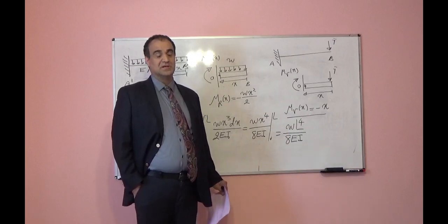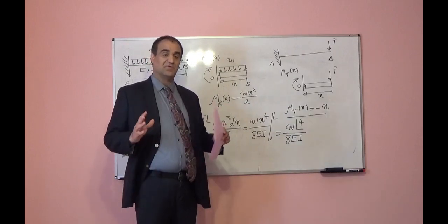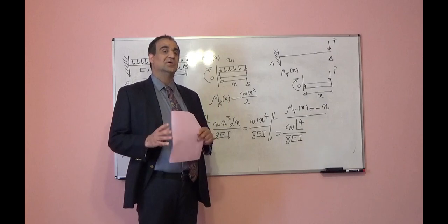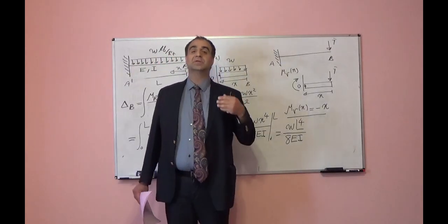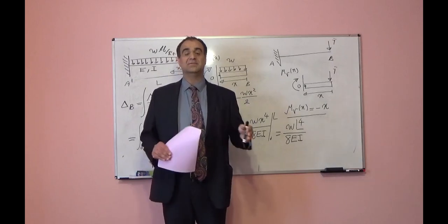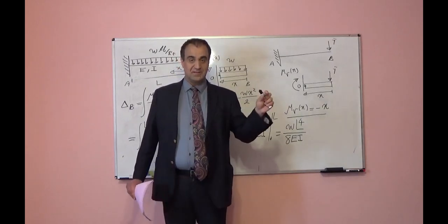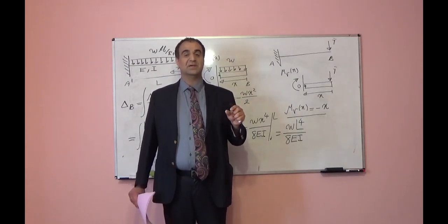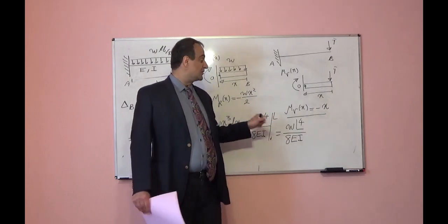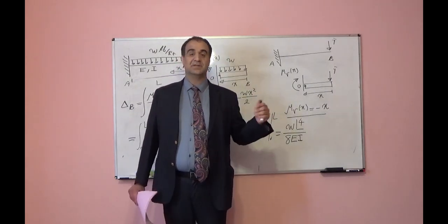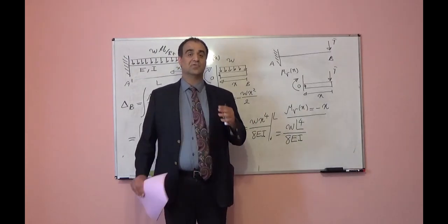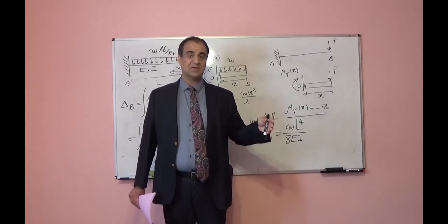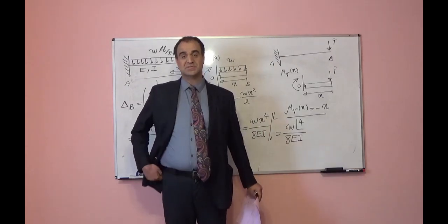For those cases, somebody before has integrated for most cases, and according to the moment diagram shape, they developed tables. So we will look at those tables and figure out the coefficient for integration. That I will explain later. For now, we will integrate, but in order to do calculations very fast, we will use those tables later on.